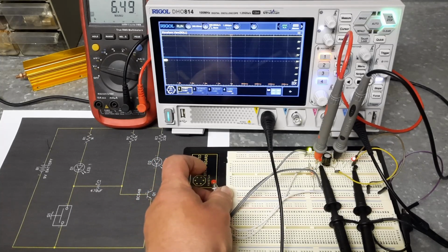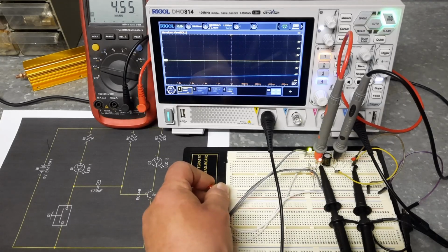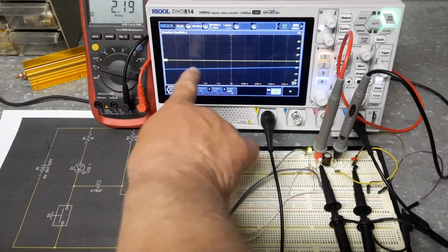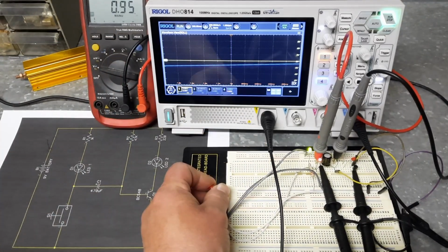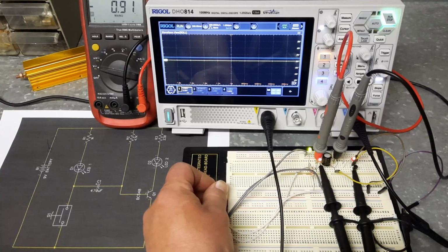So let's do it. Let's press it. As I said, this part of the circuit now looks like a negative. So that's that cap discharging. Now it's gone through 0. That cap has now got a negative charge across it, as you can see with the voltmeter. So we're going to let this go now, and something's going to happen that we're going to discuss.